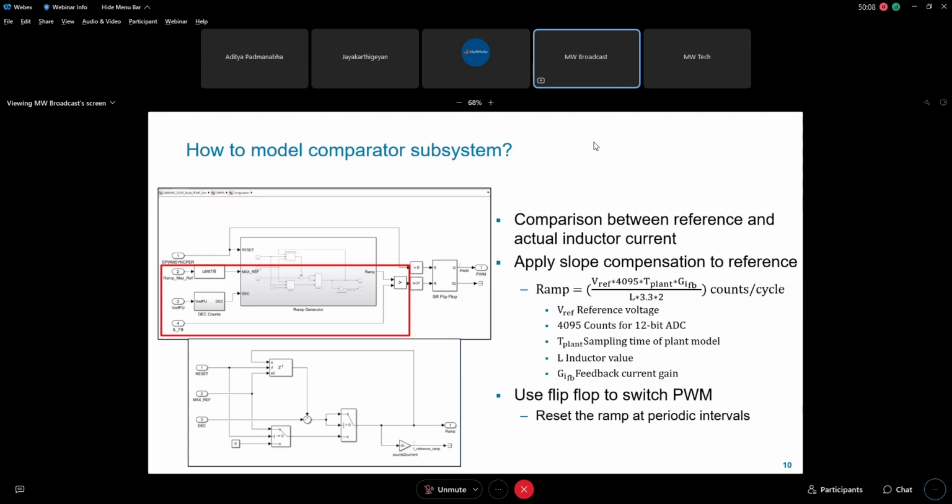The reference is generated from the voltage feedback passing through the ramp generator to create the negative ramp reference. The ramp generator involves decrementing the value starting from the max reference and resetting it back to the same value on every PWM period. The max reference and decrement amount are determined based on the slope of the ramp needed. As we saw earlier, for the best results the ramp reference must be half of the actual inductor current ramp.